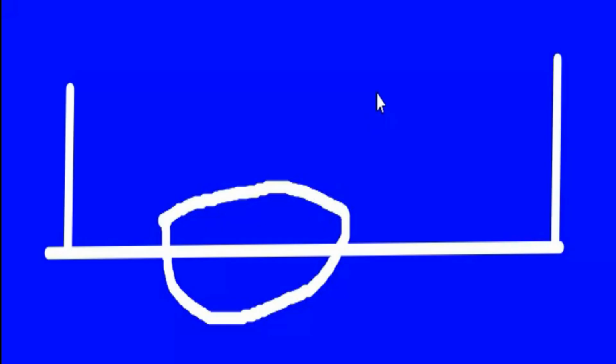Right here is the first method, in which there is a pond in between, or you can also assume a river in a similar form. Now in this case we cannot take the measurements by chain or by any other method, even a tape included. So the ranging line is supposed to be in this direction from A to B position. So let a ranging rod be placed over here and a ranging rod be placed over here. As you know, we need at least 3 ranging rods. So when you put 3 ranging rods and when they are aligned in a straight line, the ranging is complete.